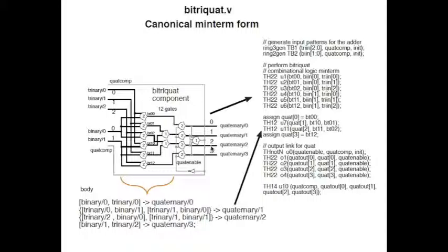So when this rail that was data becomes null, it implies that the input is completely transitioned to null, and the null wavefront has flowed completely through the circuit, and that the transition to null of the output is the correct resolution of the presented input, which is now all null. So the completeness criterion works in both directions for the transition to data and the transition to null.